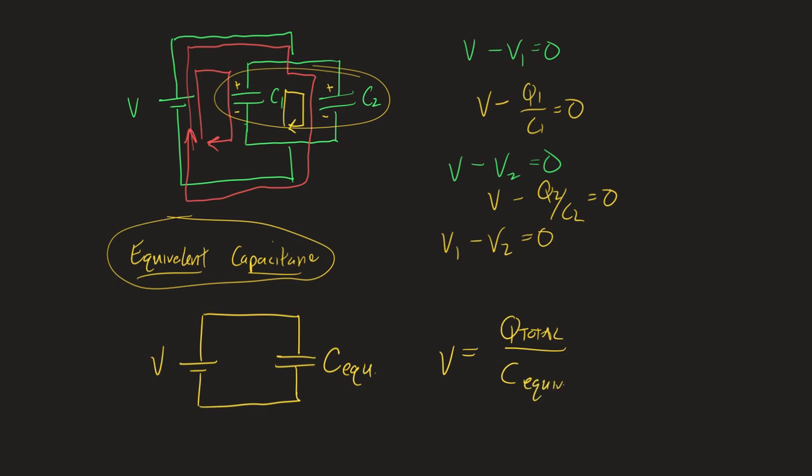Yeah. So this would be like ideal path for a capacitor? It's more like, most efficient? No, neither of those are true. It's more like what if I have a requirement where I need a certain capacitance for my circuit, but I don't have a capacitor of that size. Well, maybe there's a way I can arrange capacitors in series or in parallel that would come to the same size. That's what this is about.